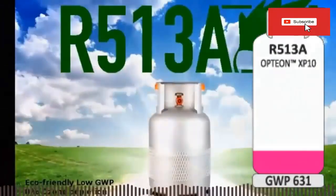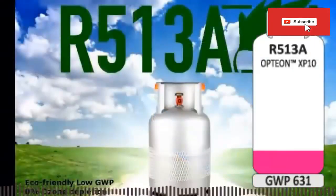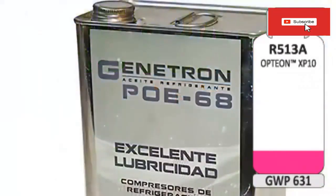14. R-513a is also known under its trade name Opteon XP10. 15. R-513a is compatible with the equipment, components, and joints of an existing installation of R-134a. 16. R-513a is compatible with synthetic oils.